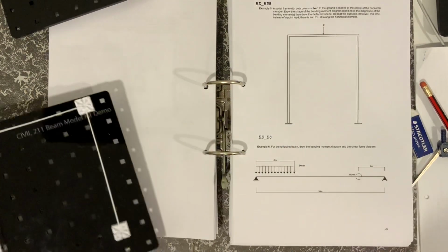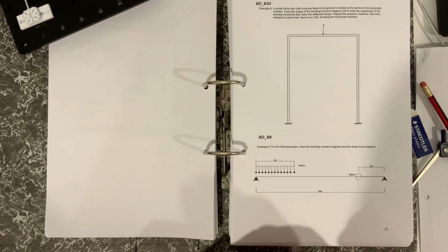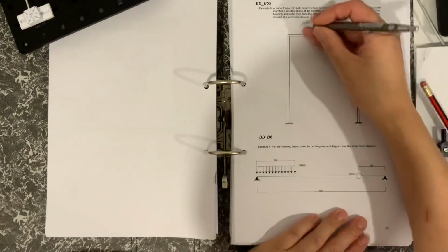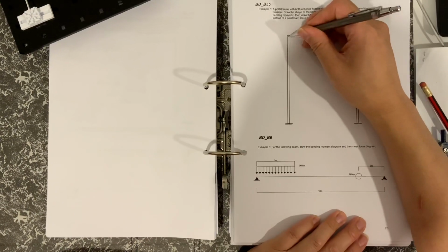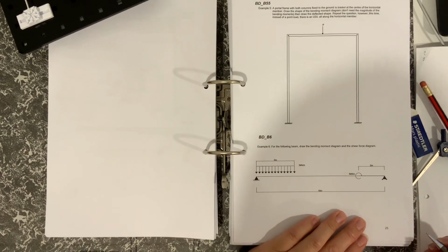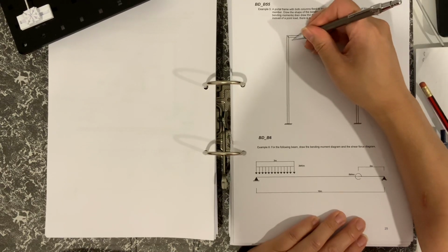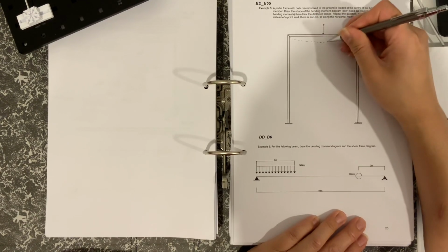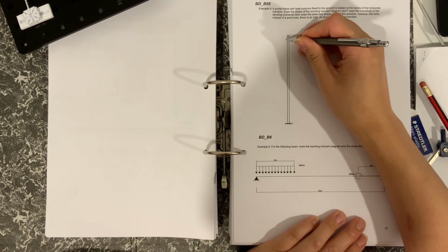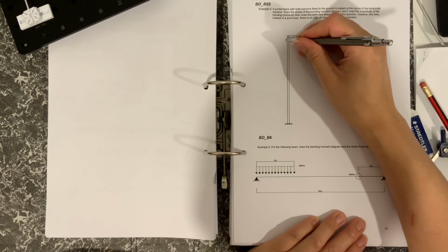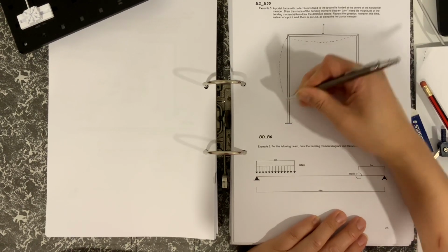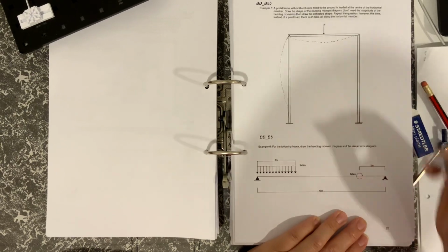So let's draw the shape of the bending moment diagram, and then draw the deflected shape. Let's start with the deflected shape, because we can see that from the kit. We'll assume that these points don't move because of symmetry, for the reasons that I've just explained. So you could expect the deflected shape to be something like that, and then that angle has to maintain at 90 degrees as we've described. So that would have to go out like that, and it would just keep on going out, and then it would have to be brought back in like that. Okay.